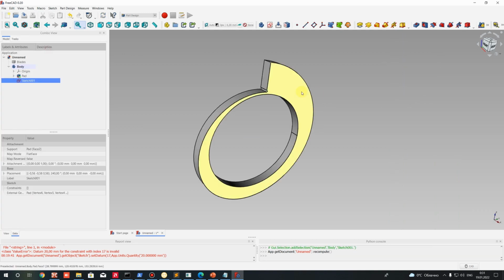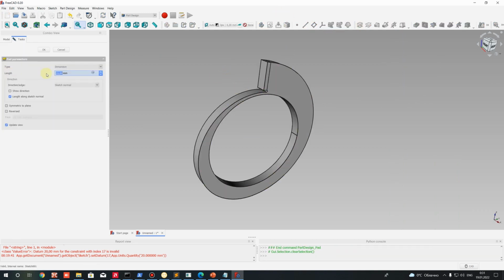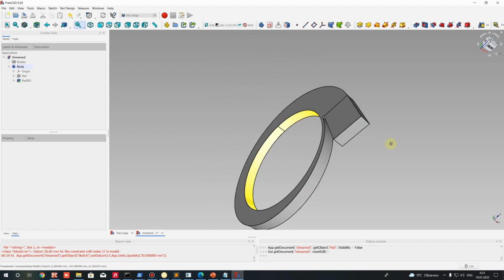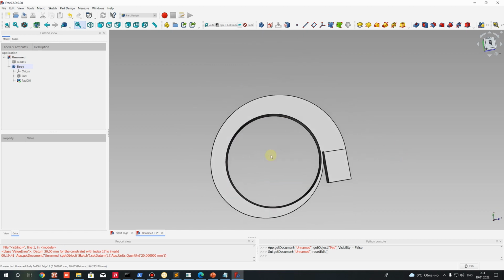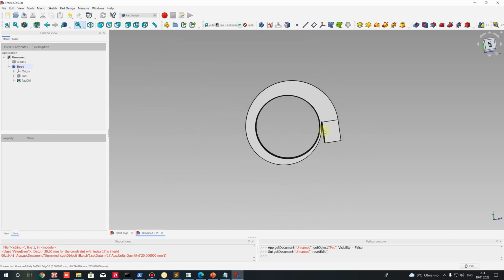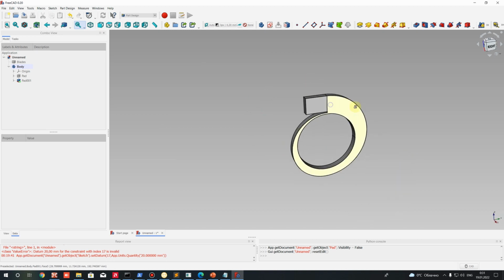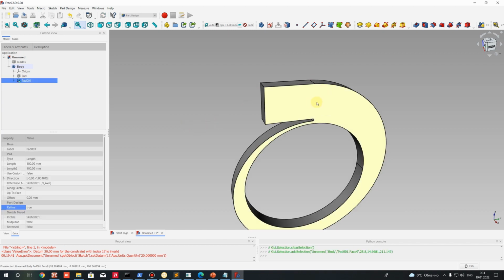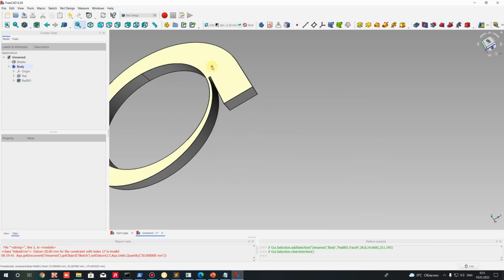And you will get the rectangle which is connected with your external geometry. So let's close it, and after that you can make a pad operation for this. For example, paste here something like this, and you will get some value for your rectangle. Let's make refine true. It will delete these lines from your geometry.